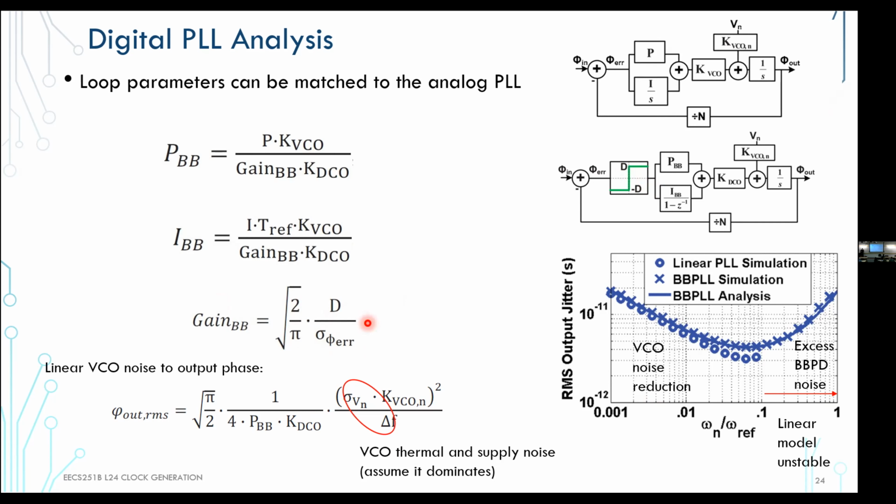What's my LSB step size compared to the thermal noise that comes in at the input of the ADC? Because thermal noise smears the signal across that LSB, and the relationship of the two tells you what the gain of that phase comparator is.